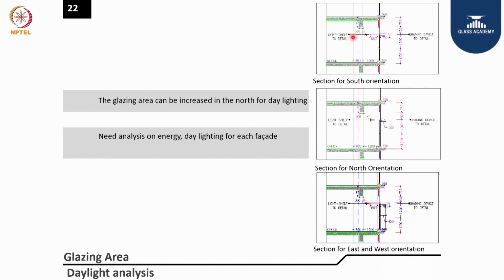And a very important thing is, when you have a glass, even though you have shading devices, the daylight penetration on the perimeter will always be a little higher, in terms of 1200 lux as you can see here. But this is a little strange for an occupant sitting at the facade or adjacent to the perimeter area.